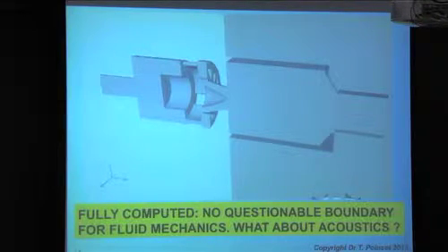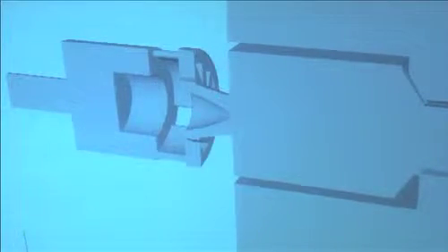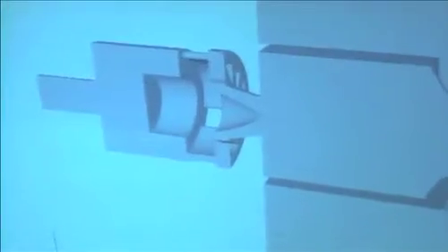Apart from that, you don't have to do anything because you solve the flow in the swirler here. I want to mention that too, because I know quite a few groups which begin the simulation here. So they drop completely that. They start the computation here where they impose the velocity field. They impose the rotation, they impose the actual velocity field. It's much easier, of course.